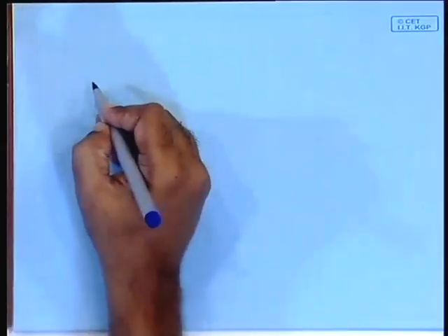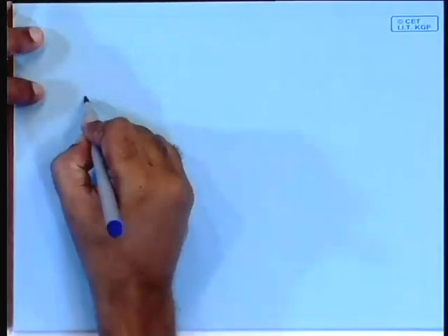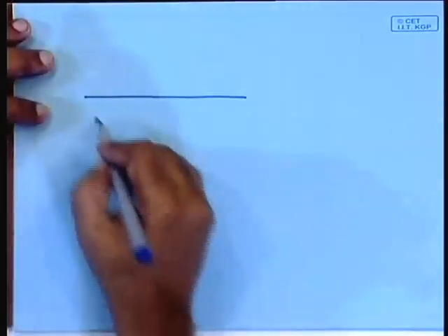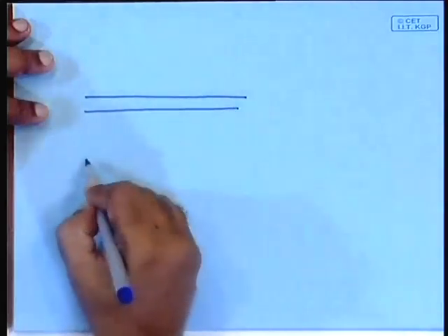Another major source of inefficiency is simple reflection, because the top surface is flat and quite plain, there will be reflection, and in fact 40% is lost by reflection. 40% is quite a large amount. Fortunately, we have ways of arresting much of it. How is it done? The idea is quite simple. Supposing you have, say, a semiconductor layer, you have the N over P.